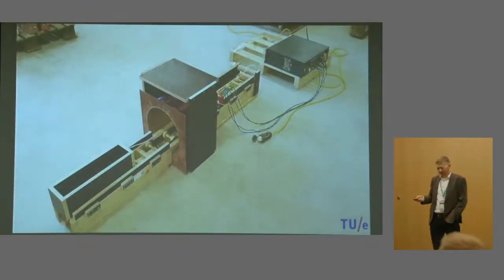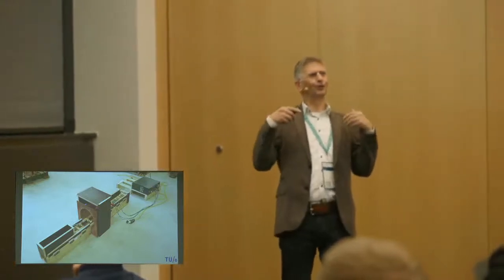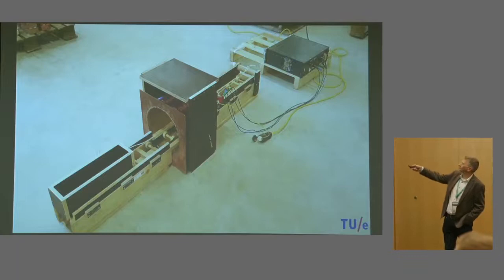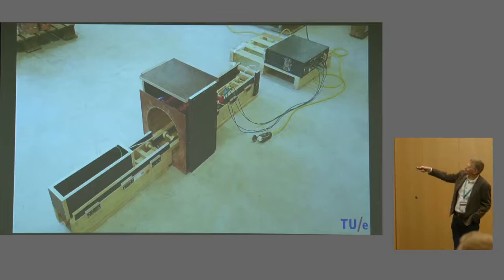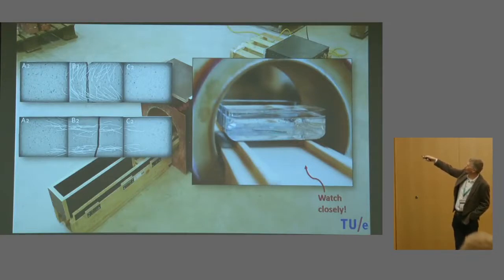Now, there was one student who said, but if you print in this direction and you place a filament and all these fibers come, they will be aligned. And he's correct. These fibers are aligned so far, at least with us. So he tried to see if he could orient them in a certain manner. So he made a magnetic field, so a coil with copper wire, electric feeding on top of that, and then the concrete in here and drag the concrete through. And if you see on this small sample with an oil, so this is the coil, and there is a fiber, and the fiber in the oil is now rotating.